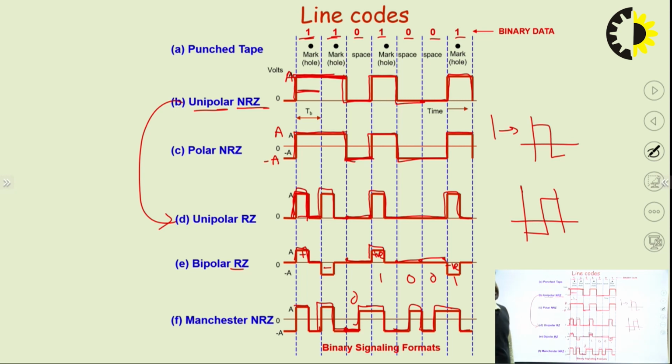So in this line coding technique, we have done different types of line coding. In these two lectures, we have done unipolar, polar, bipolar, and scrambling. Scrambling overcomes the bipolar synchronization error. In the next session, we will do the PSD, power spectral density. We will compare unipolar RZ, polar NRZ, and bipolar NRZ.